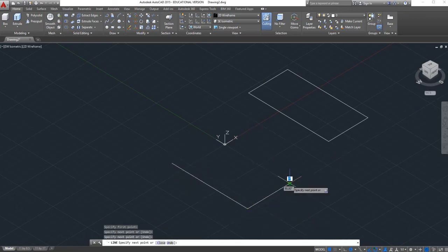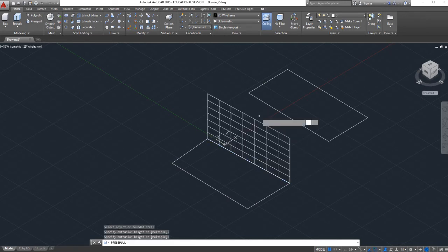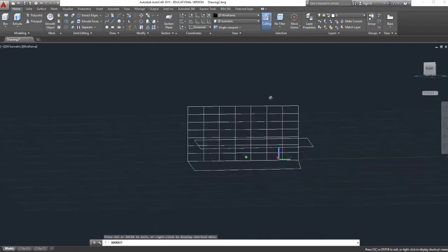So here are single lines that I am making a simple box with. So if I do press pull and I click it inside, you see the entire rectangle will highlight. Or I can choose one line and you see that I have a grid. The grid indicates that just that line and only that line has been made 3D.